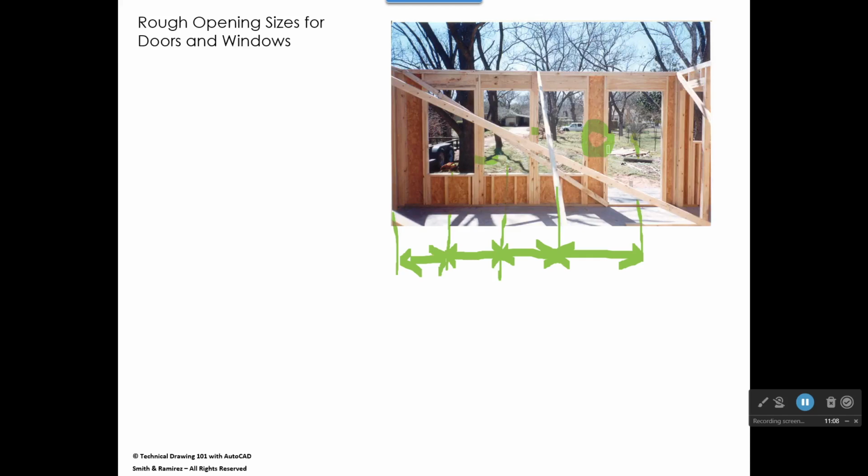So the switch itself is housed inside an electrical box that has to fit between these 2x4s in here. And so a designer has to take that into consideration when they figure how many switches they will need, because you don't want the electrician calling you from the job and saying, hey, I don't have enough room to fit all those electrical boxes in this wall the way that you drew this plan.